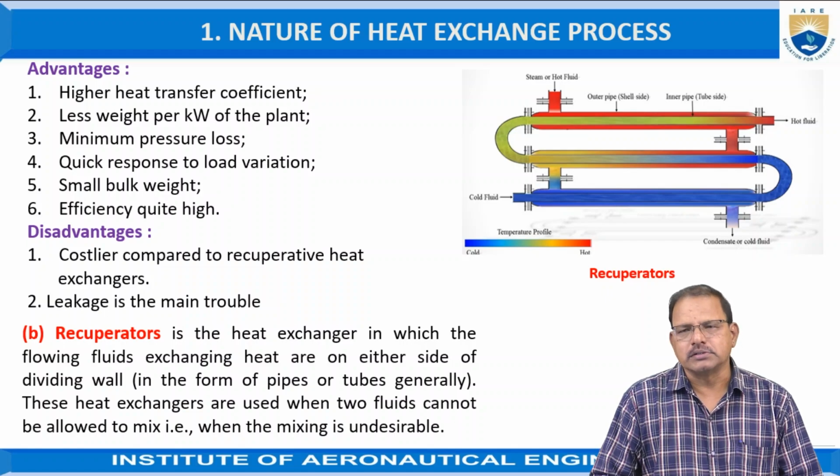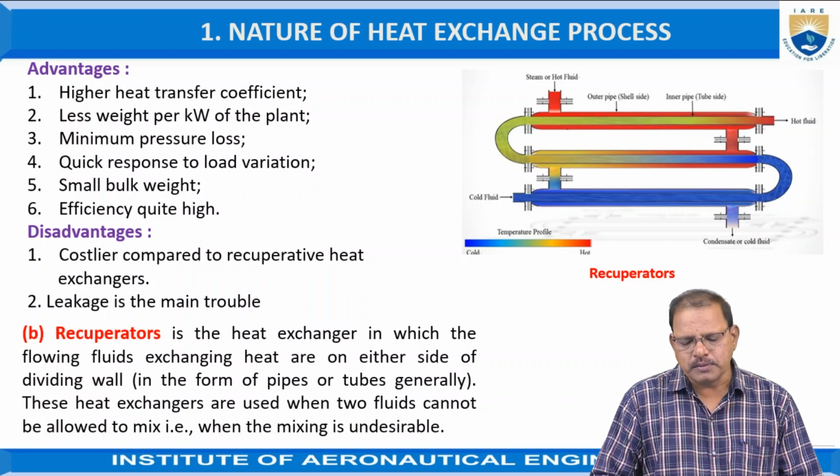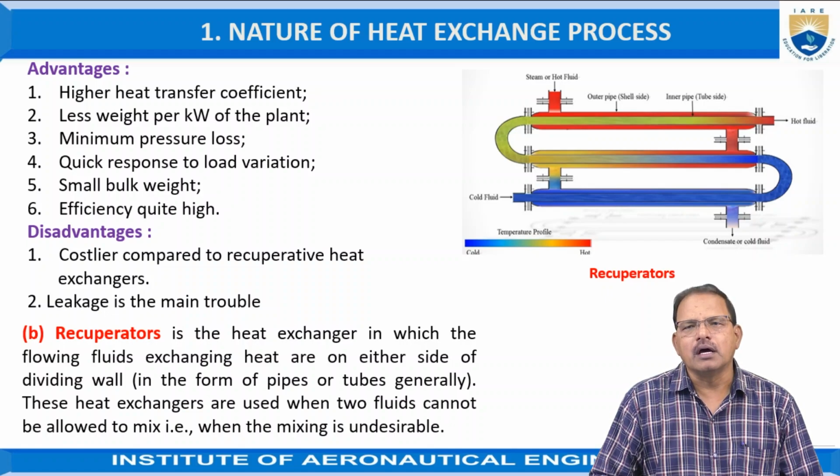Okay, recuperators. These are heat exchangers in which the fluids exchanging heat flow on opposite sides of a dividing wall, generally in the form of pipes or tubes. These heat exchangers are used when two fluids cannot be allowed to mix, when mixing is undesirable.